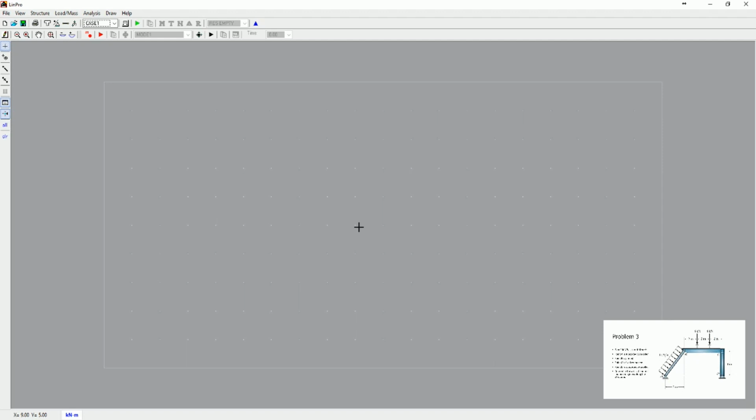The next step is to define the joints. Select the joint icon on the left. Select this point. Then we move by 3, 1, 2, 3, 1, 2, 3, 4. Then we begin by moving by 6, 1, 2, 3, 4, 5, 6. And we go down by 4, 1, 2, 3, 4. Our joints are ready.